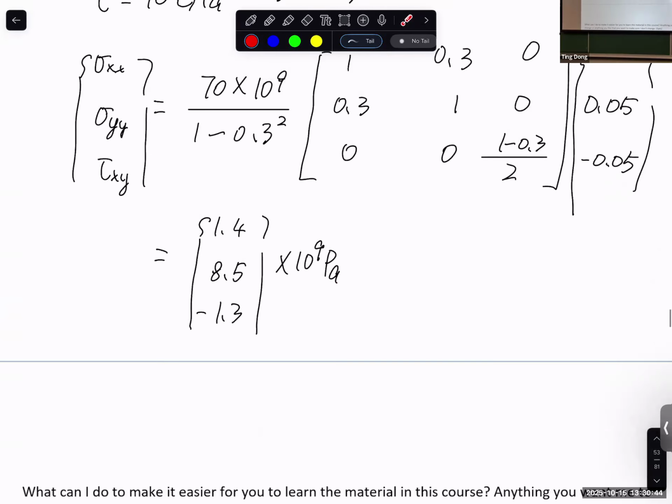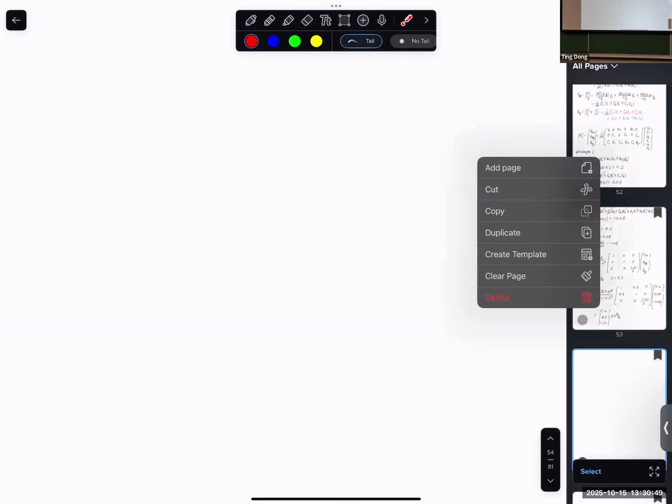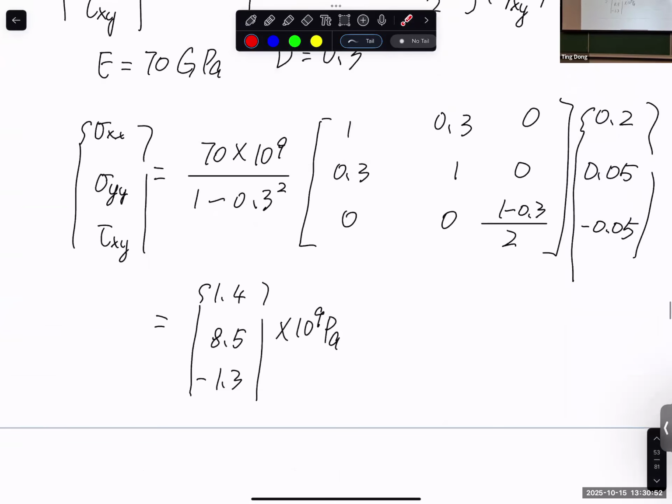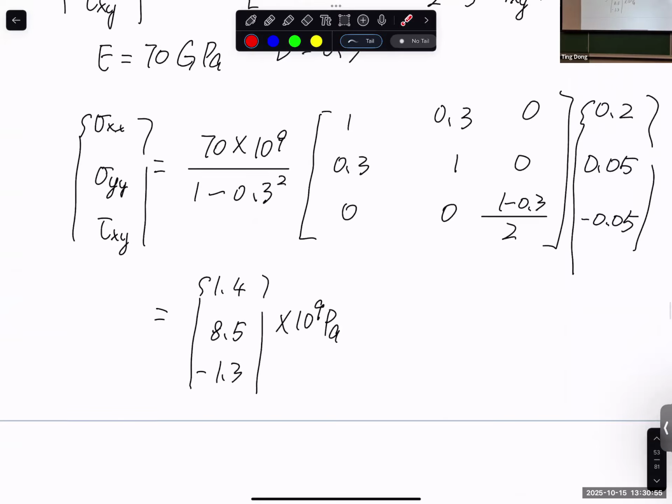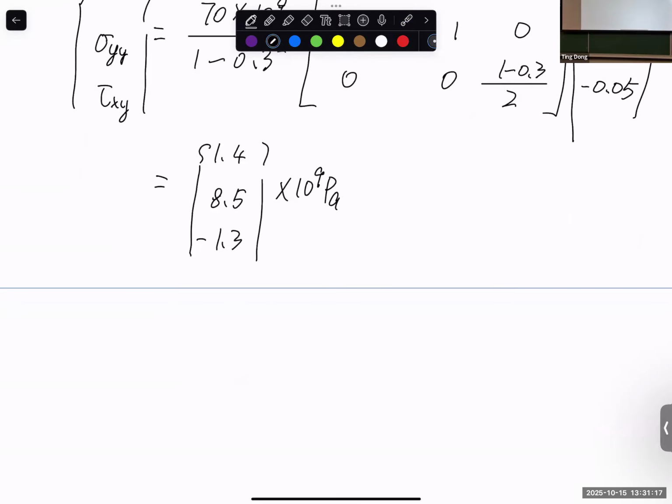So let's move on to a new topic. We talked about interpolation, how to calculate strain, and how to calculate stress, and all of these are based on knowing the nodal degrees of freedom. So now our question is how to calculate the nodal degrees of freedom. Back to KQ equals F. We know K, we know F, so we can calculate Q. So let's first figure out how to find the stiffness matrix for the CST element. It's in chapter 6, section 3.3.